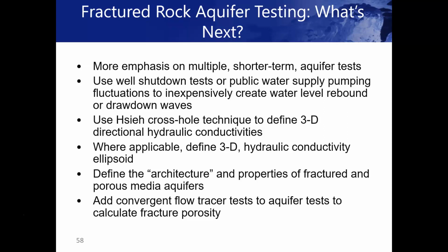The problem, just from a practical perspective, is a water table aquifer, the storativity is defined as specific yield. So you have a much higher storativity and quite a variable storativity. So it's hard to lock in on what the specific storage is, because it's a combination of essentially specific storage, but also aquifer dewatering. It's a water table aquifer. So it doesn't really lend itself to testing of water table aquifers.